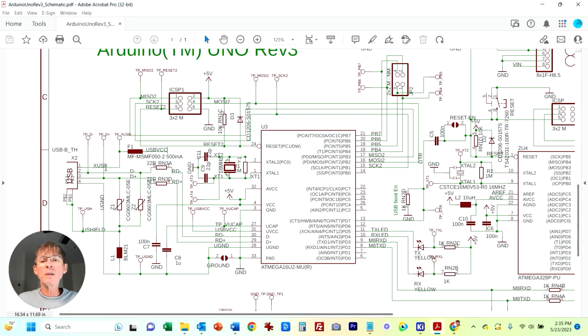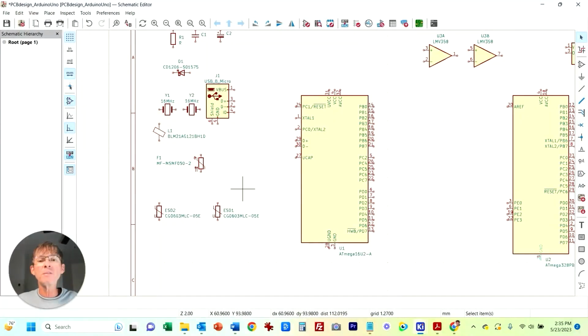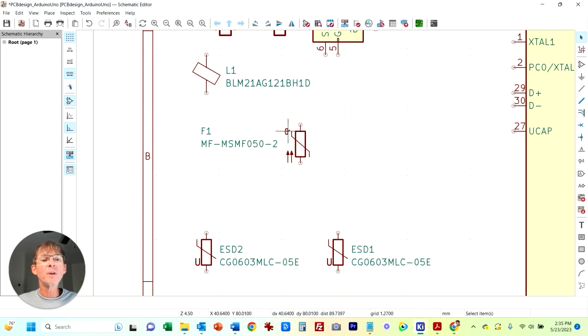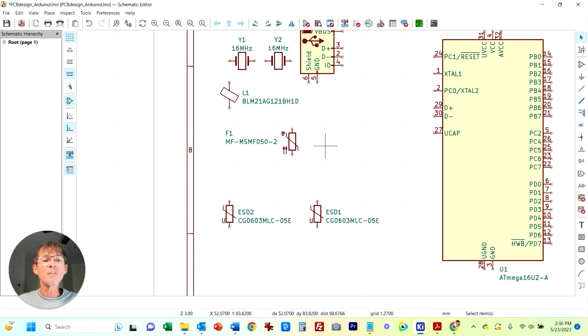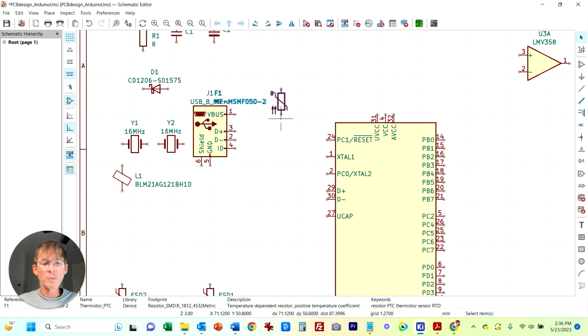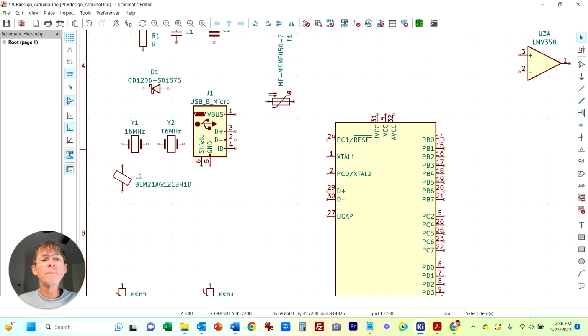Okay, so the USB power supply comes off, and it's going to go through our PTC fuse, which is this device right here. The symbol is a little bit different. This is not necessarily a very standardized symbol for a PTC fuse, so for my symbol here I just went with the default that's used for KiCad, so it may be a bit different. I'm going to rotate this around, and we can just route this here.